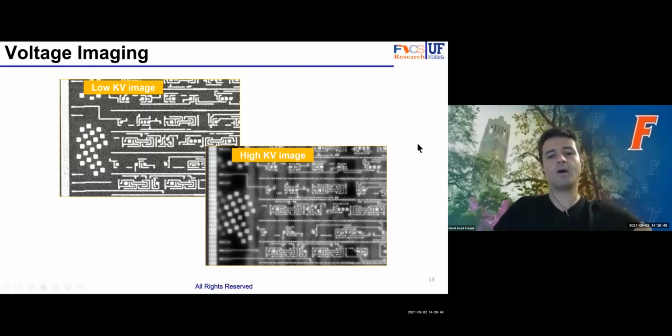If this convolved image can be extracted in this layer with the algorithms, we are basically saving 2 steps of delayering, because in a low kV image, here is one set of information. There has to be one delayering step. Then we get the contacts, all these circles, another level of delayering, and then we collect the metal 2 layers. All right. So if all the features can be extracted from an image like this, then we are literally saving months or more than that, depending on the size of the chip. And by the way, we are not there yet. So the complexity and the noise and a lot of false positives are happening here.